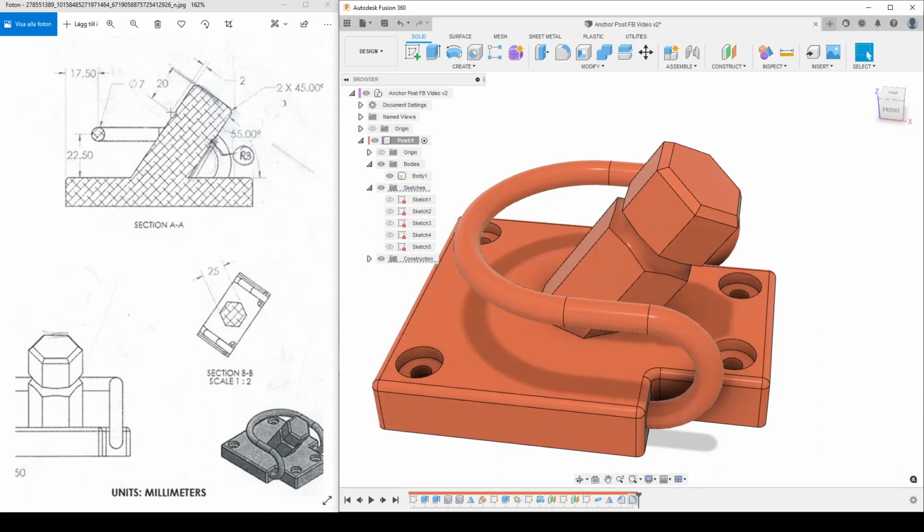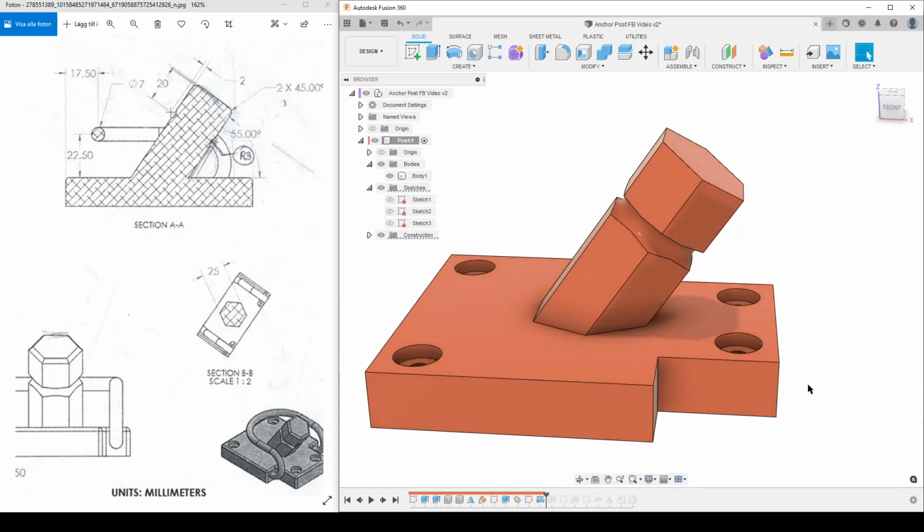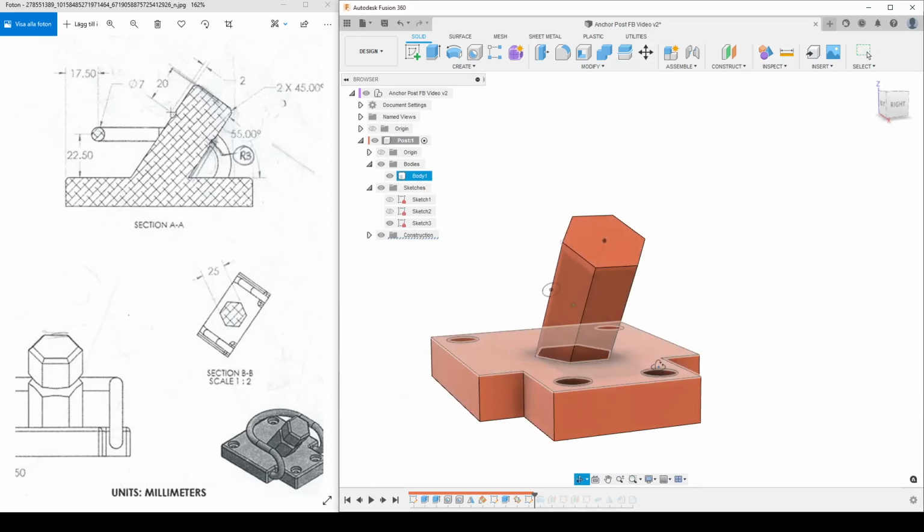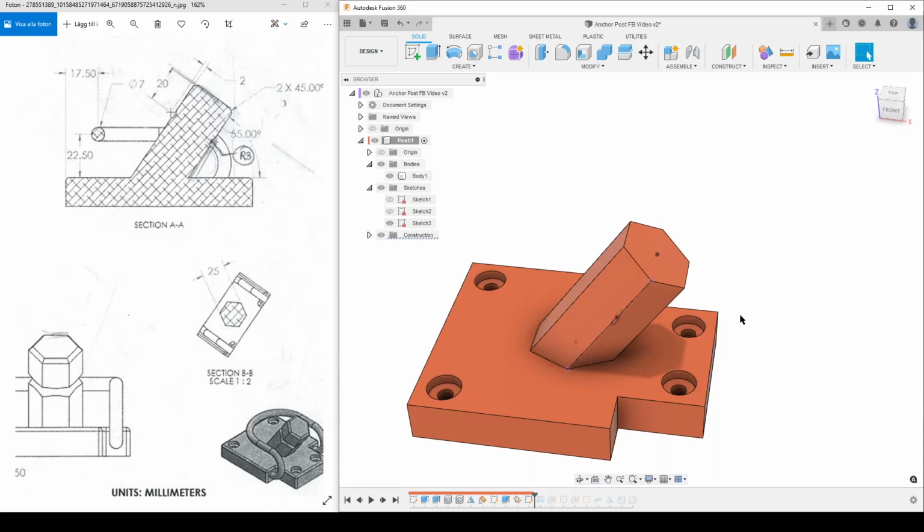To avoid errors, I will now move the timeline back to a Revolve command. I want to skip Fusion doing recalculations of everything after here, or do that at the end, just simply move the timeline forward. Once again, check I'm in the correct component, and this is Revolve. Oh yeah, let's back it up before, because the problem is, let's highlight the last sketch. This is this one here. This is totally in the wrong direction, it's on the wrong plane, everything is wrong about this sketch.